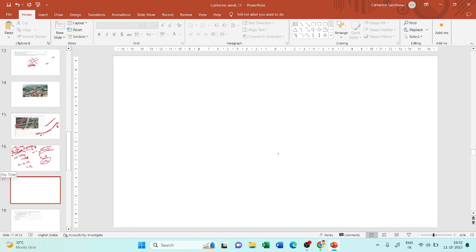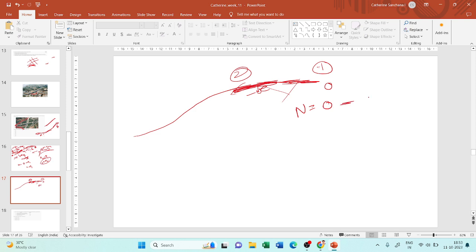Okay, so again we will take this ramp, and this time we will come from here. Your first slope will be 0 and this slope will be negative, right, because it is decreasing now. Now if you find out, this is my first slope and this is my second slope. If I find the deflection angle, it will be 0 minus of minus n2, which will be plus n2. So this is a summit curve.